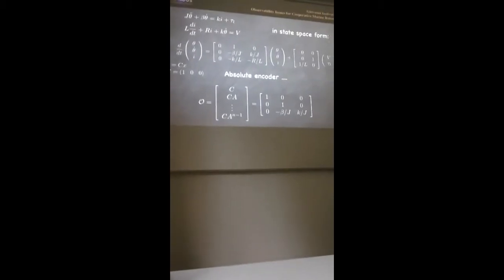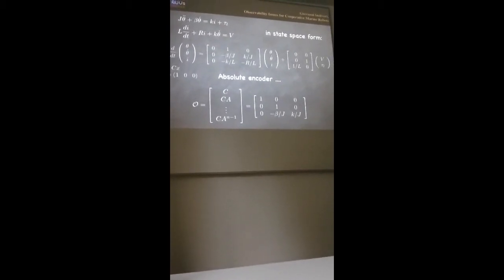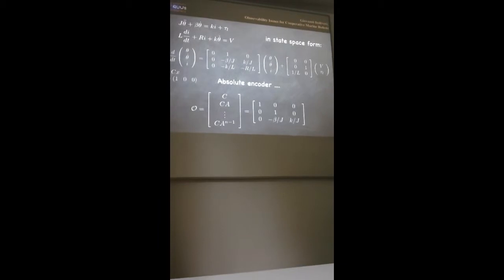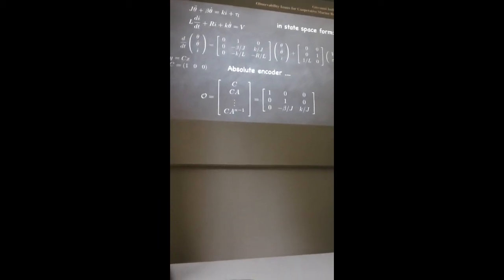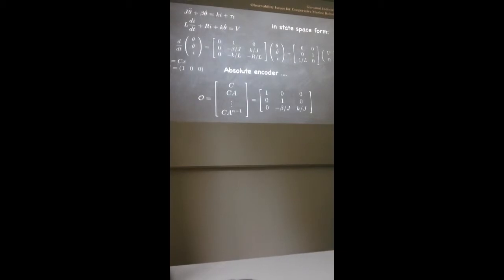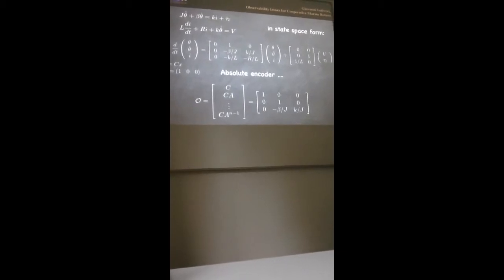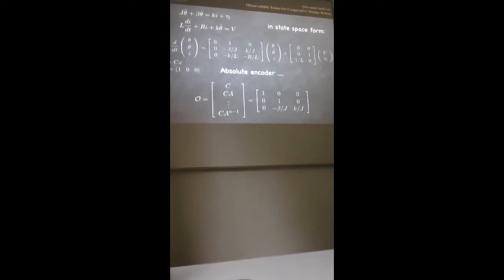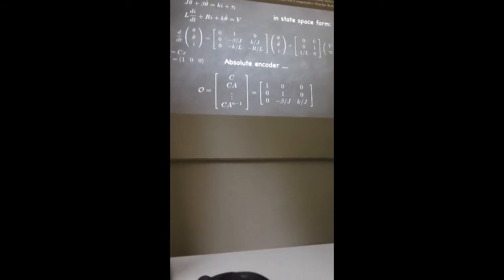Now, yeah, you have an absolute encoder. This is not happening on propellers, but it happens in industrial manipulators. So if the same motor, you put it on, instead of on a propeller, on an industrial manipulator, you usually measure joints with absolute encoders. So you actually measure the angle of each joint, okay?